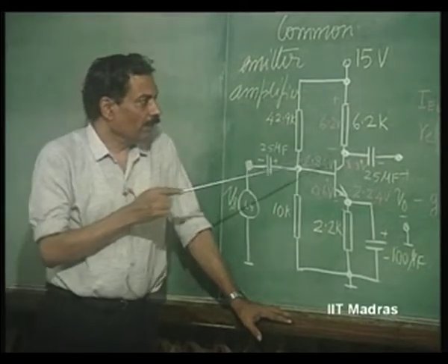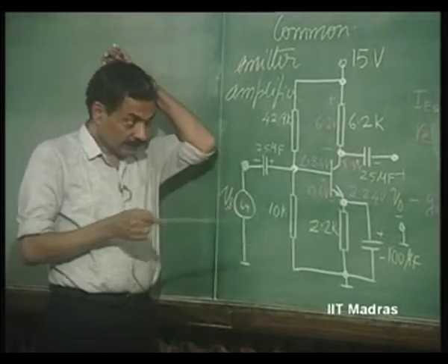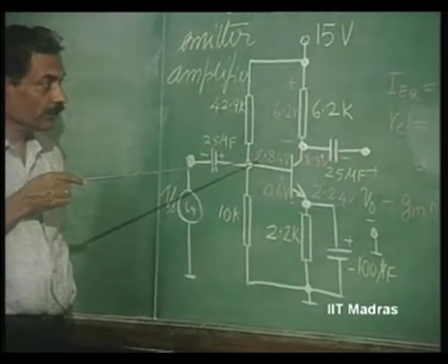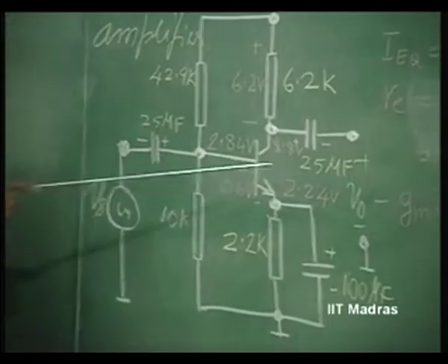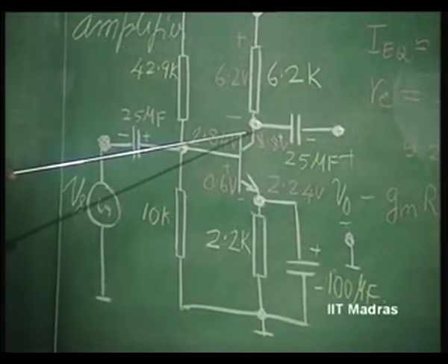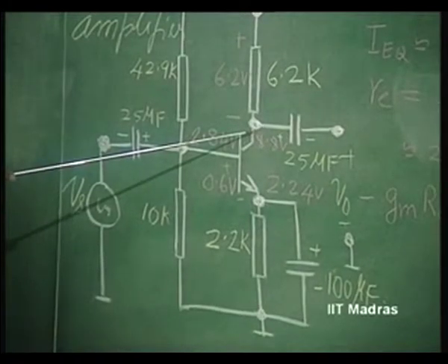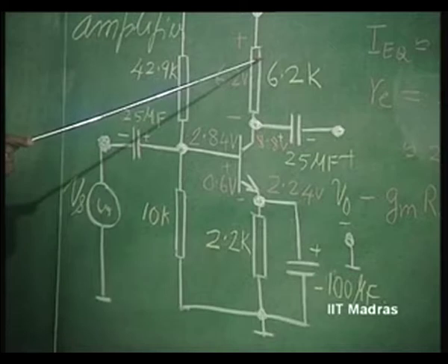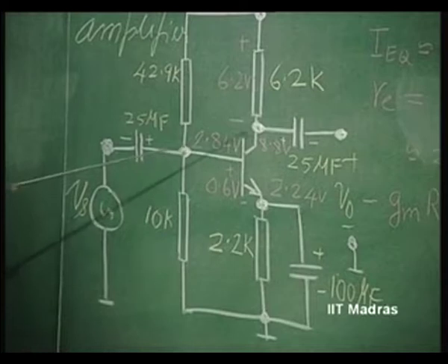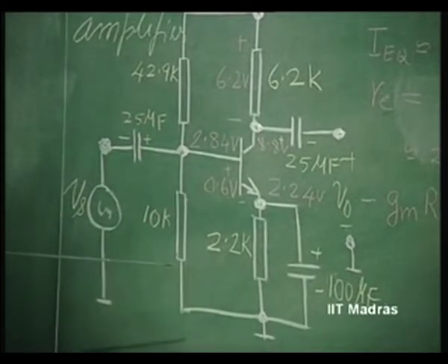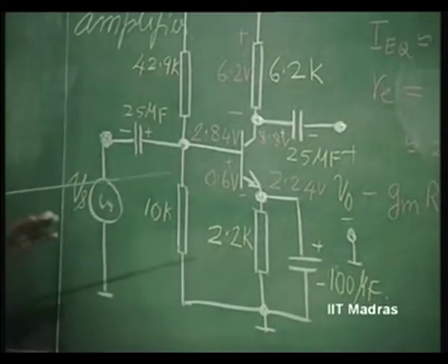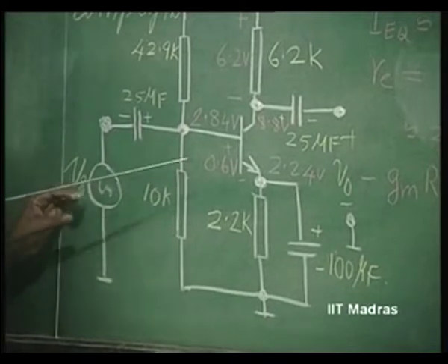Now we will illustrate the large signal effect. This is biased to VCEQ of 6 volts here, and the current I is about 1 milliampere. Due to the limits, one is the transistor going off, that 1 milliampere into 6.2 K. So on one side it is 6.2 volts, on the other side it is again 6 volts. It is almost symmetric swing possible. That means both the saturation limit as well as the cutoff limit should begin almost simultaneously. So let us keep increasing the signal.